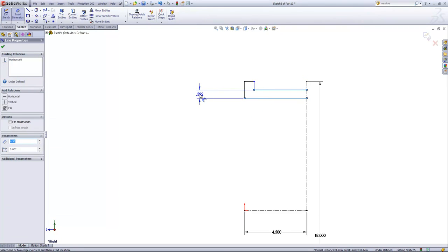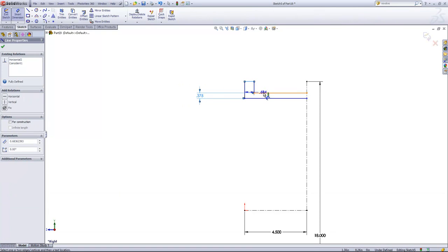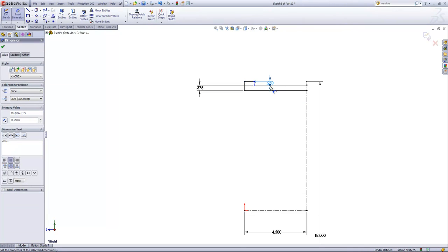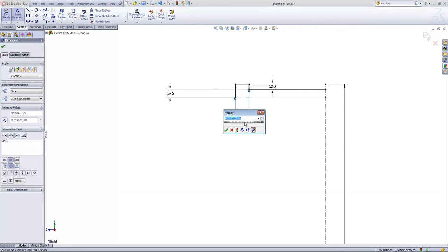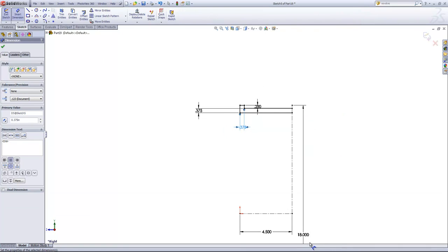This is going to have a thickness of 3/8 of an inch. And a distance from these two of 1/4 of an inch. And lastly, this will also have a thickness of 3/8 of an inch. This represents half of our profile for the rim of the wheel. If you can imagine, this is going to extend out to the other side and revolve around this center axis. Before we do that, we're going to add in the profile for the hub and the spokes of the wheel.